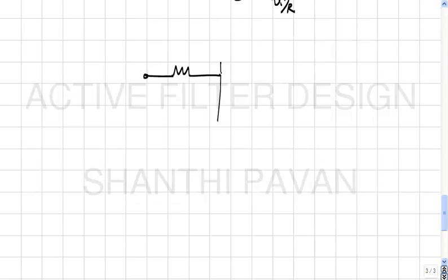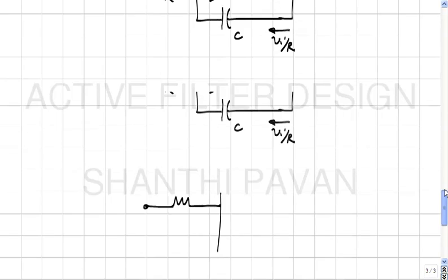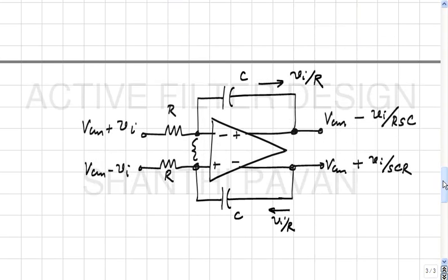Yes. No, it's coming from some other signal, right? Some differential source is driving it. That should have a well defined common mode. Yes. This is coming from two voltage sources, isn't it? It must have a well defined common mode.